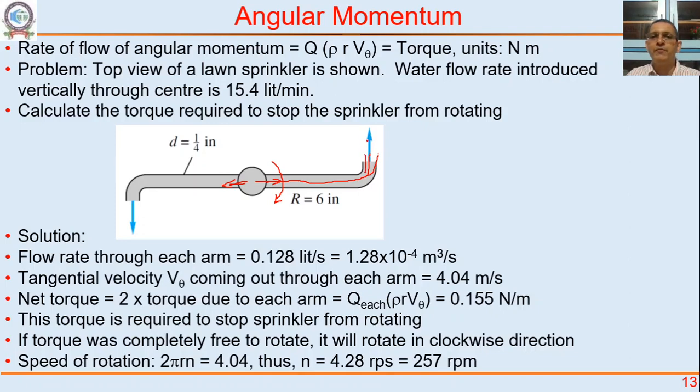at a velocity v. What would be that velocity? That velocity would be this volumetric flow rate, 7.7, divided by the cross-sectional area. Cross-sectional area is pi by 4 multiplied by this diameter squared. That's the cross-sectional area here. That's the cross-sectional area here.